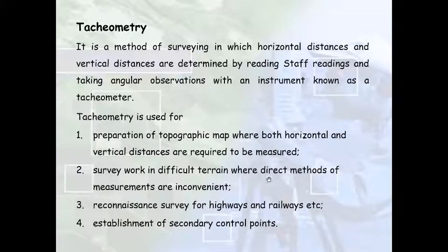So that really paces up the work, especially in traversing, where you want to obtain both horizontal control and the vertical control. That means you need to take both the readings at the same time, and you can do that with the same instrument. So in vertical control, the instrument can work as an auto level as well. Basically, it really paces up the work and reduces the amount of different instruments that you need to use.